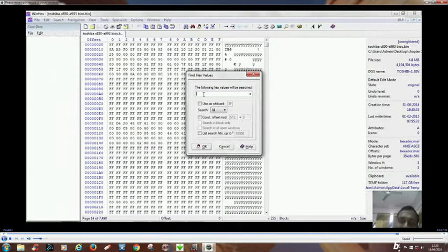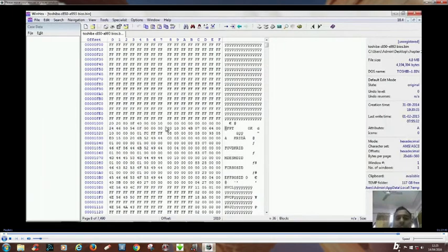Always note, in any kind of BIOS, your AMI region would start from 244650. This is the crux, 244650, and you can see from this point your AMI region data is there.